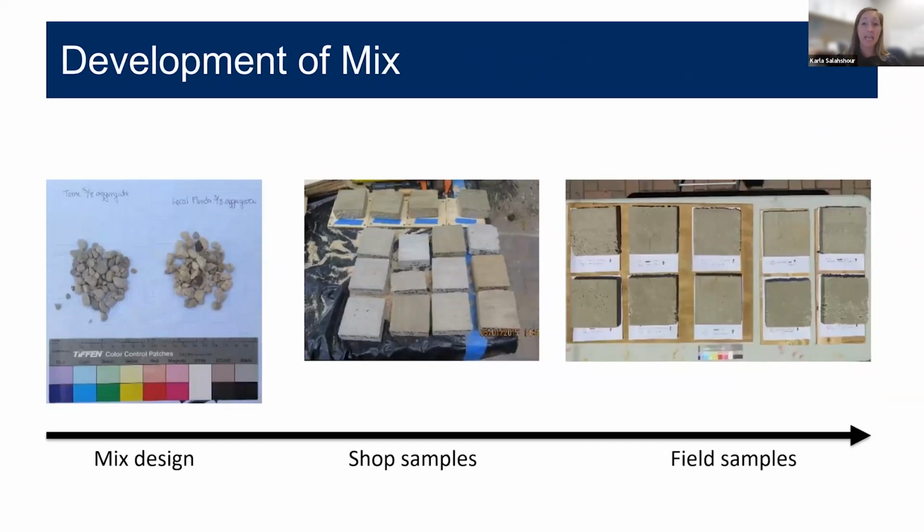Some of our findings can be used to develop repair mix designs. So we prefer to understand the material of what we're attempting to fix or repair, hence why we collect the samples, we perform laboratory testing to really know what material was there originally.